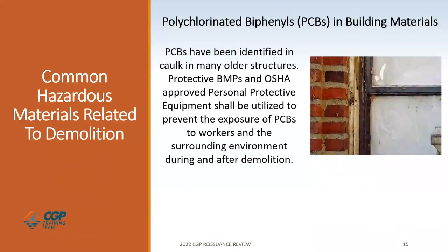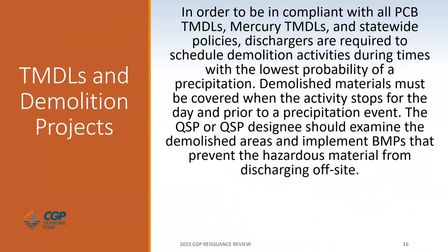Lastly, polychlorinated biphenyl, or PCBs, have been identified in many older structures. Protected BMPs and OSHA-approved personal protective equipment must be utilized to prevent exposure of PCBs to workers and the surrounding environments during and after demolition. If the construction site is located in an area where a TMDL has been designated, the project must be compliant with all PCB TMDLs, mercury TMDLs, and statewide policies.